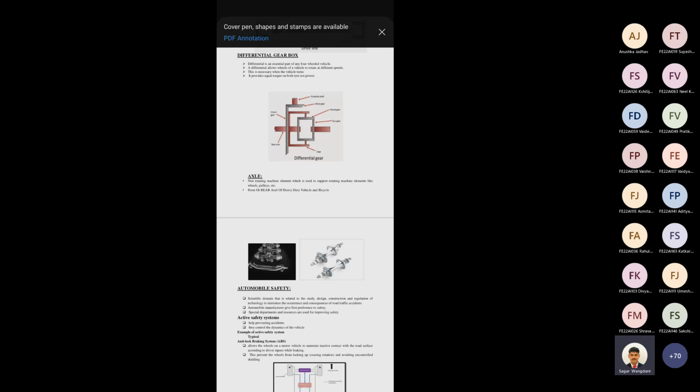Through the bevel gear, it is connected to the crown gear. And on the crown gear, cages are there. That black color we were seeing is nothing but the cage, right? And the rear axle. Through the cage, that is connected to your planet gear and sun gears. When the vehicle is running on a straight line, the entire unit works as a single unit. When the vehicle takes a turn, the planet and sun gears rotate as per resistance, and both wheels have different speeds of rotation, right?